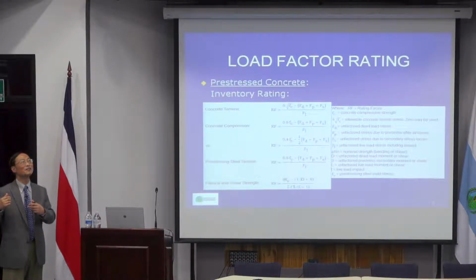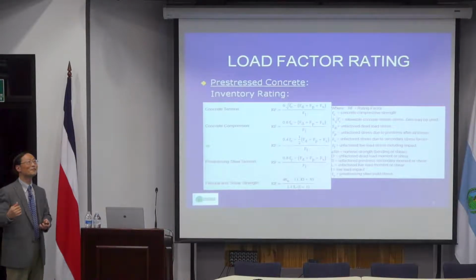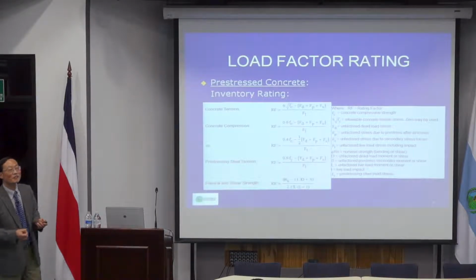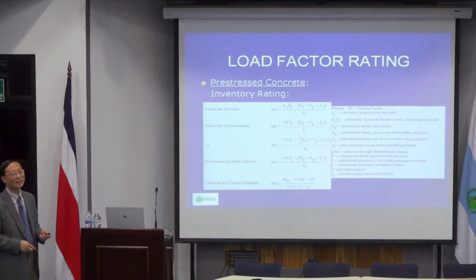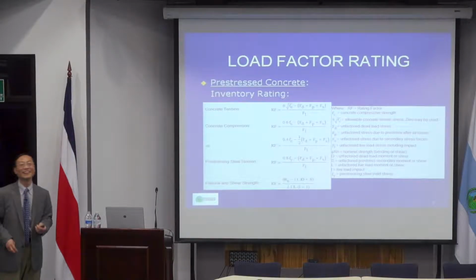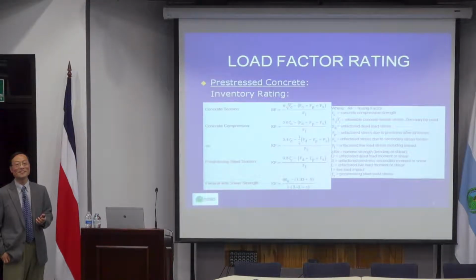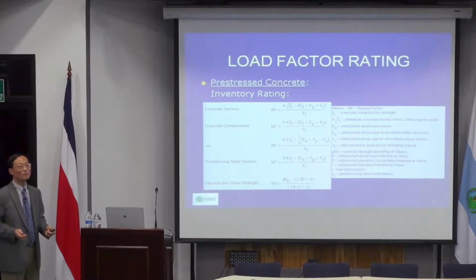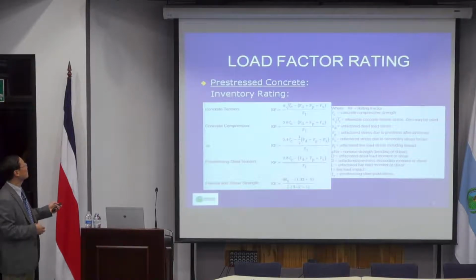So that's why when you design pre-stress here, what kind of design code do you have? Do you have your own design code for bridges? In Costa Rica, do you have your own bridge design code, or use a Euro code? Oh, you use AASHTO. Now you use LFD. Okay, that's good. Did you use the standard specification before, like allowable stress? Okay. So it's very much the same. We have a common language here, and that's why you also need to rate for concrete tension and concrete compression.